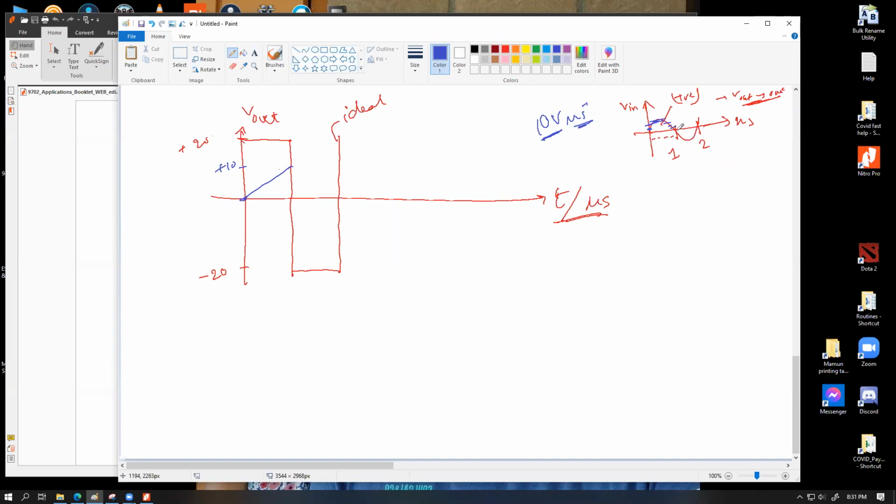And then whenever the op amp is going to start going down, this voltage has to become 0 and it should then become negative. But here's the problem. This is once again a downward cycle of exactly 1 microsecond, which means to reduce to 0 and to become negative, the op amp only has 1 microsecond.